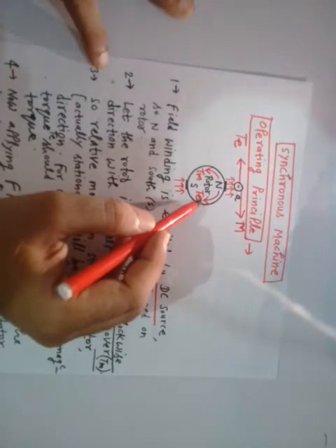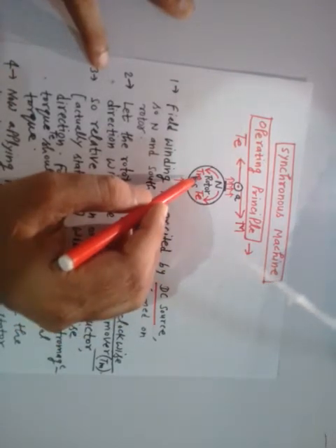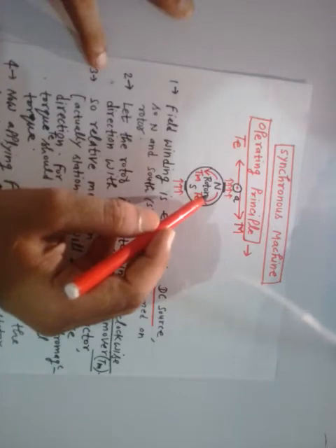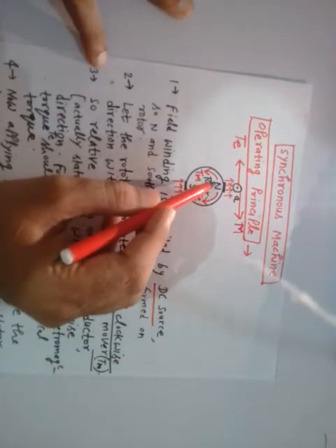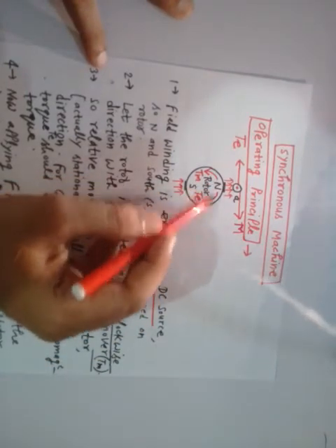Suppose the load has increased, and due to this the opposition of the electromagnetic torque to the mechanical torque increases. So the rotor, prima facie, appears to slow down momentarily, for a very small time period. But it will not remain in the same condition.